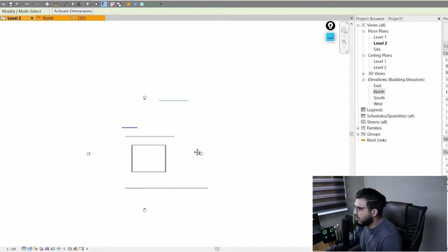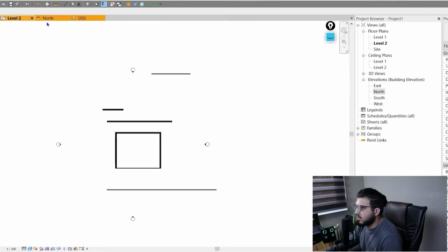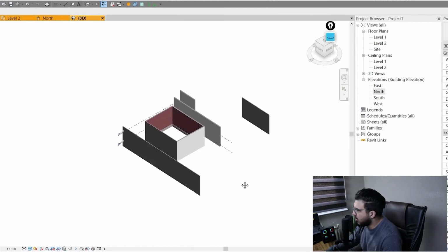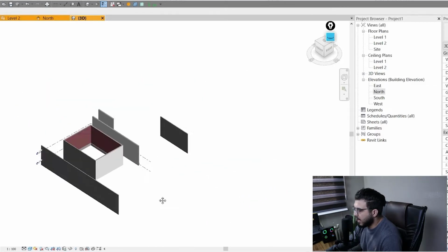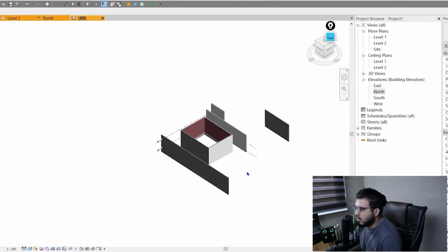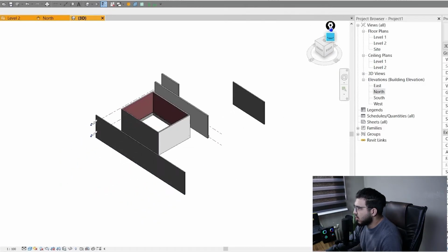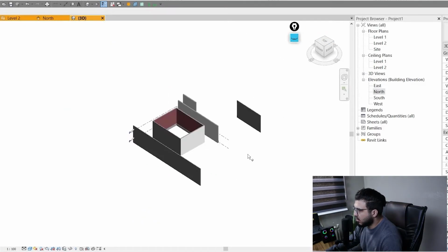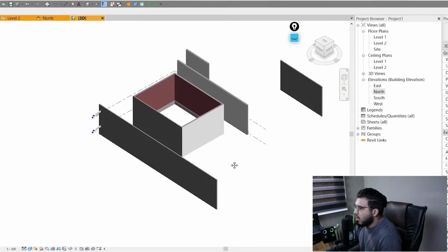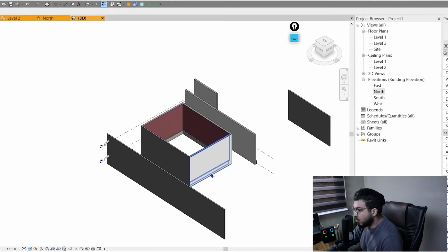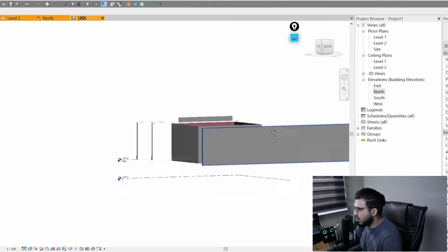These are the kinds of navigation in 2D, but in 3D, for panning, you can use the mouse wheel button, and you can pan in your views. And then you have zoom in and zoom out. These are really easy navigations. You can zoom in with your wheel again. And for rotating around, you need to hold down Shift and use the wheel button to rotate around the objects.